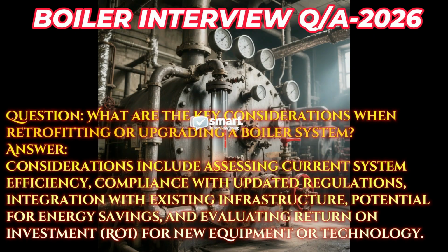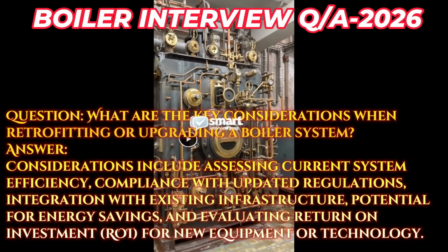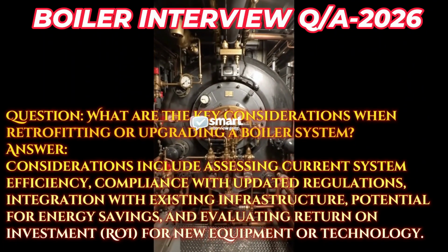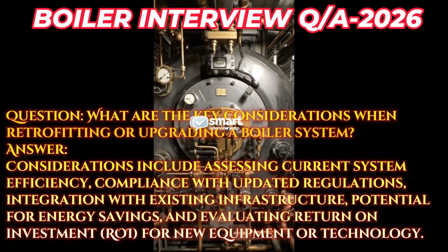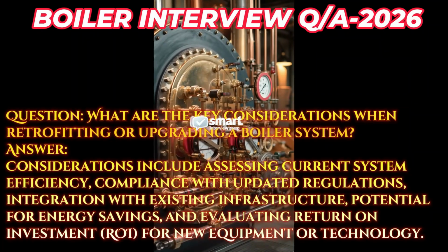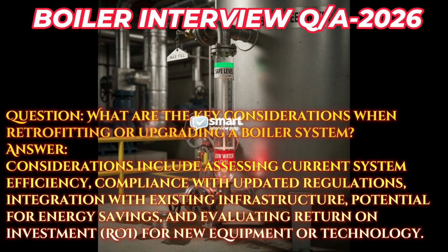Question: what are the key considerations when retrofitting or upgrading a boiler system? Answer: considerations include assessing current system efficiency, compliance with updated regulations, integration with existing infrastructure, potential for energy savings, and evaluating return on investment, ROI, for new equipment or technology.